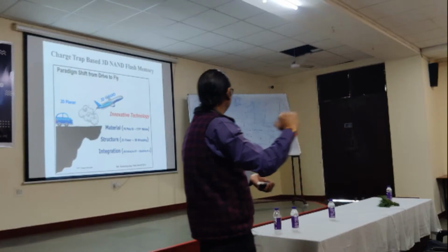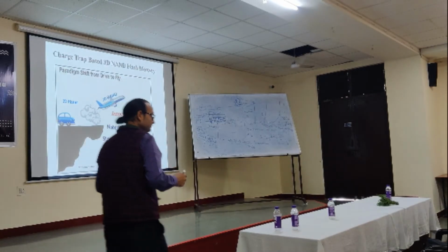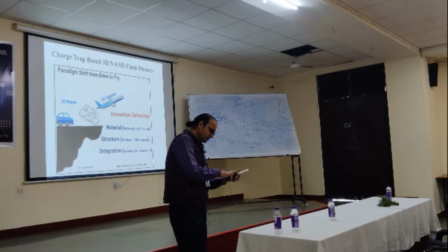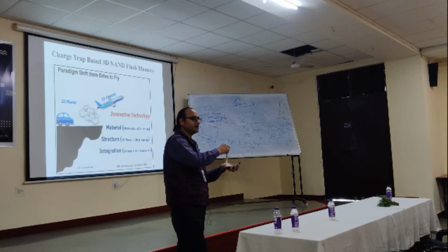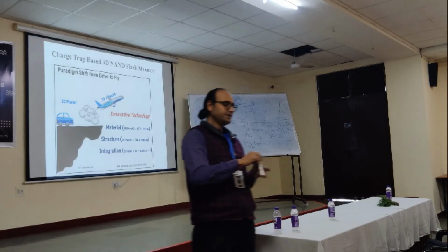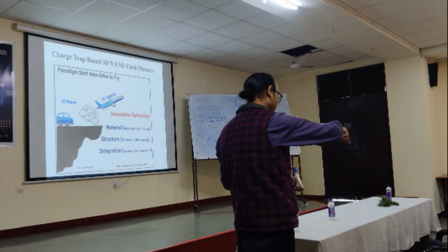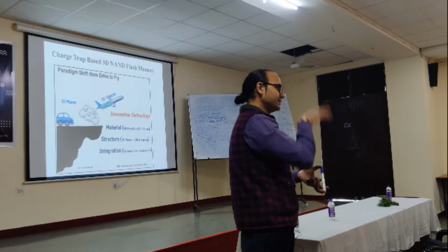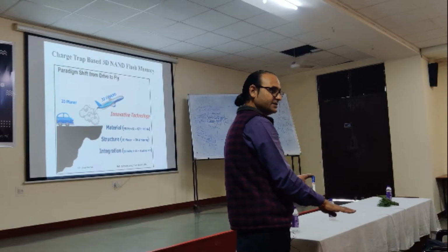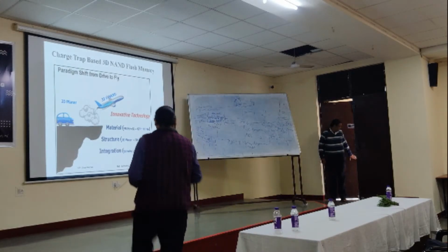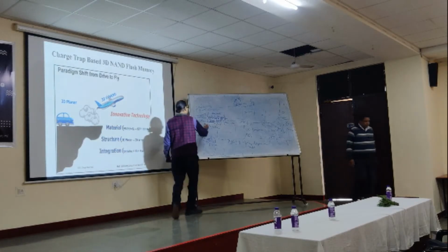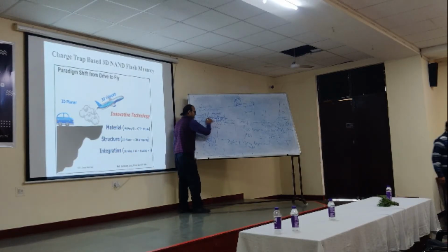So yes, almost. But what happens is, rather than in this direction, memory strings are designed in this direction. But how? I will let you know how that is done. First of all, holes are etched in the wafer. Downwards, holes are etched, right? And then different layers are deposited. Whatever was required, like this. We had substrate, we had oxide, we had this trap layer, oxide, metal.